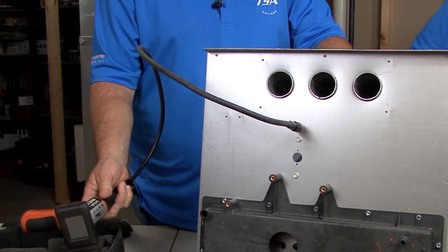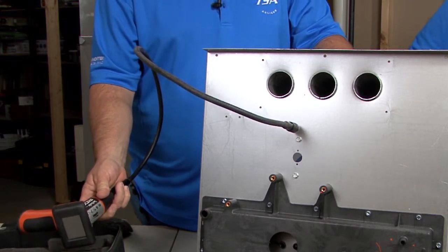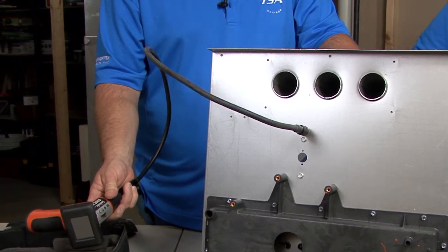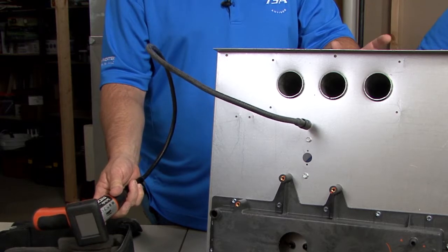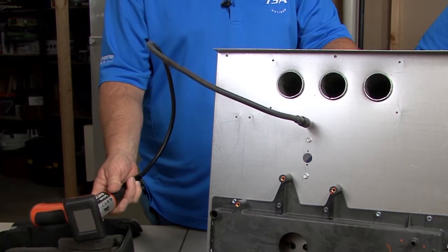So that's why I defer back to the smoke. I mean, if we got even a small hole in there, you should be able to pick it up with this smoke. Obviously, if you got a bigger hole, you're going to get more disturbance to your smoke. If you got a smaller hole, you're going to get less disturbance to the smoke. So there is a little bit of an art to watching that smoke inside that heat exchanger cell and determining whether or not you actually have a breach.